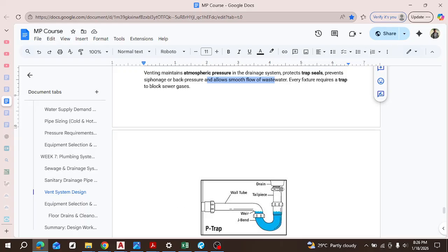So now when somebody turns on the water and washes their hand or whatever, it flows in here. Now this water trap is called a P trap because it's shaped like a P. This water trap prevents that bad air that forms while the flow is going out from coming out into the fixture, right? So it basically forms an air trap and prevents air from coming out, right?